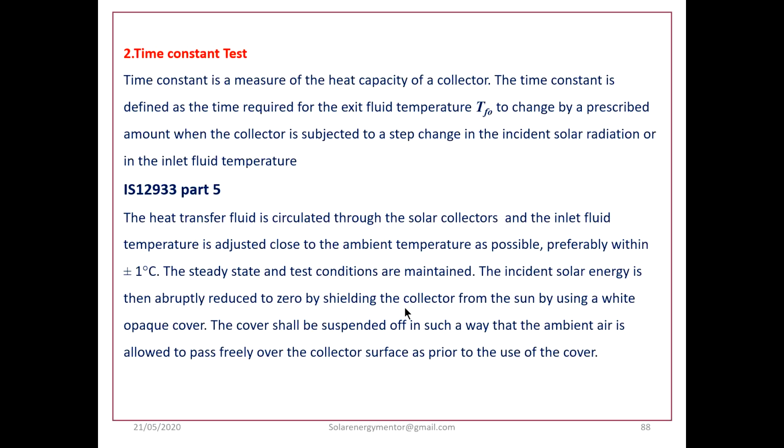Now the steady state and test conditions are maintained. This T_FI must be maintained at 28 degrees Celsius while ambient is showing 27 degrees Celsius. Now the incident solar energy is abruptly reduced to zero by shielding the collector, so we have to pull a cover over the collector, shielding it from the sun using a white opaque cover. The cover shall be suspended in such a way that it is not just put on.